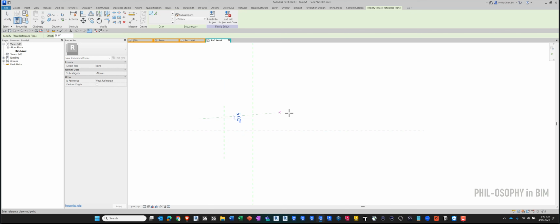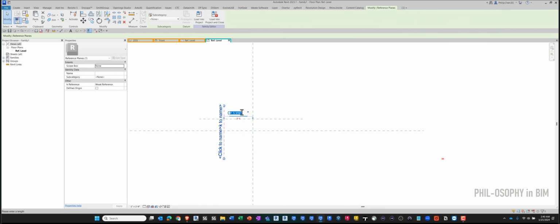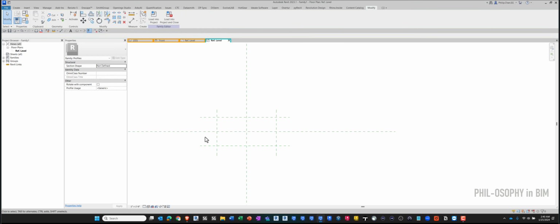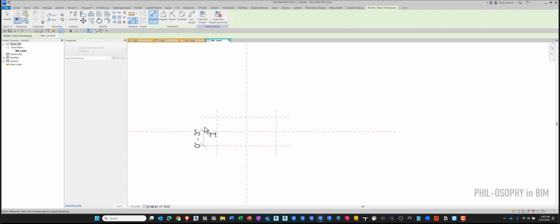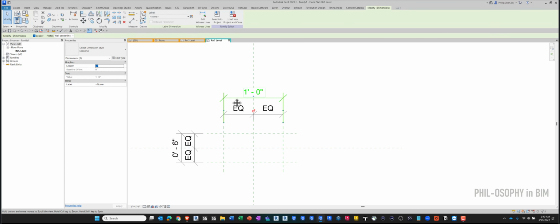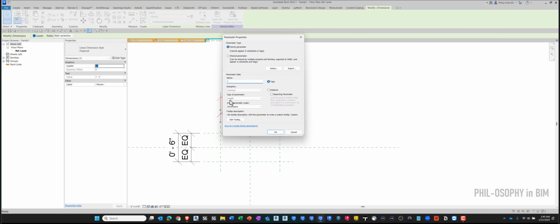I'm just gonna go ahead and lay out some reference plane here, and I will keep this a 6 inch, and then mirror it the same that I would do it from here. I would keep it 3 inch and mirror that. And I wanted to make sure that this line work that I'm using in the profile can be parametric. So basically, I'm just simply laying out some groundwork, and I'm converting these dimensions to parameters such as width.